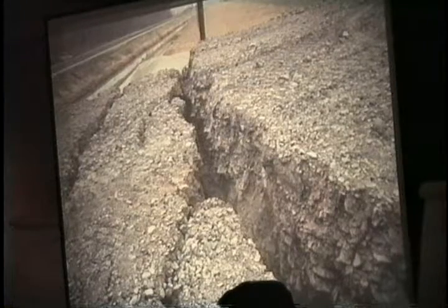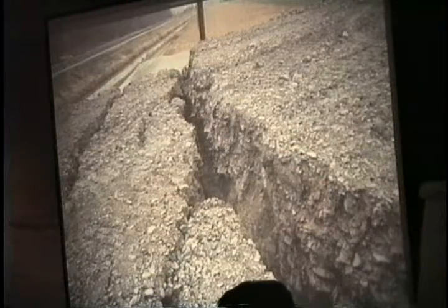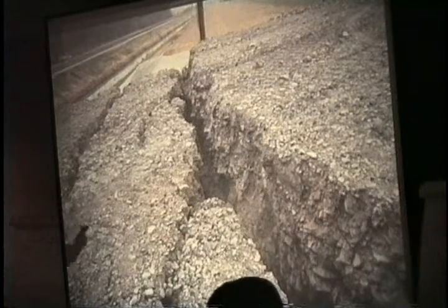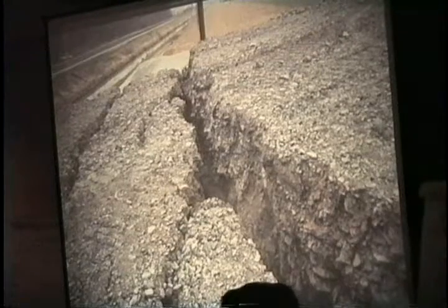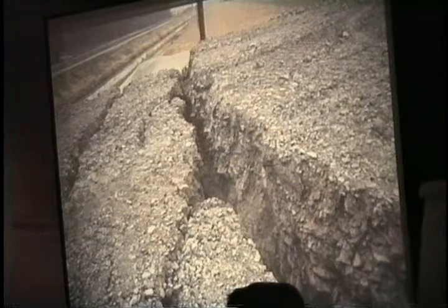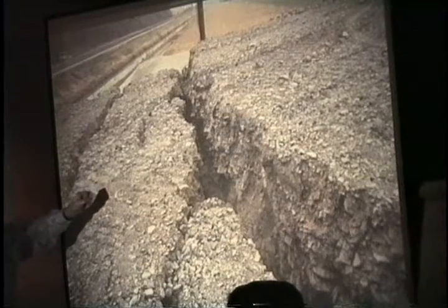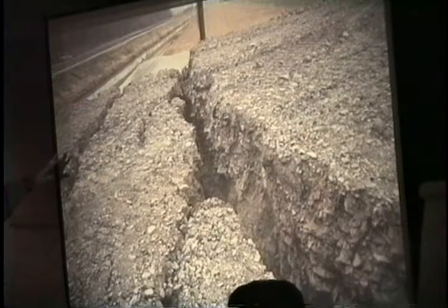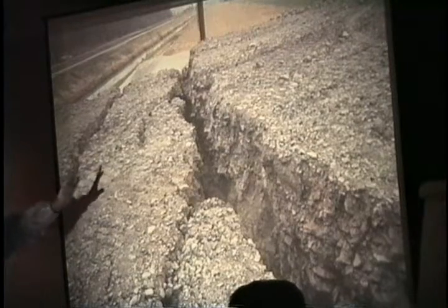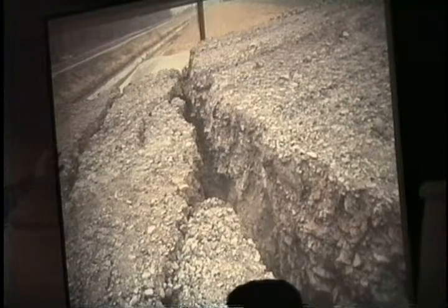I mention that because it ties into what I said before about back calculations. To assume that soil is uniform is risky. Using good engineering judgment, tying into the geology. Well, guess why this thing moved? Okay, visualize it. It moved towards the river.